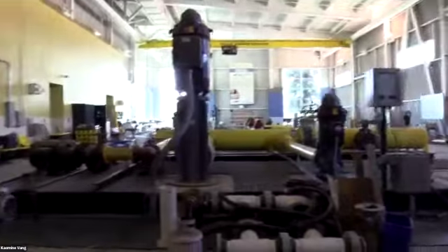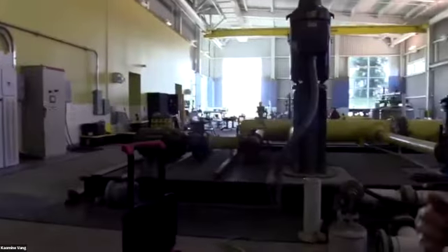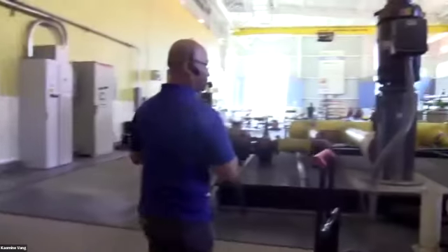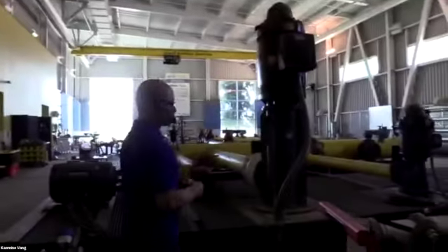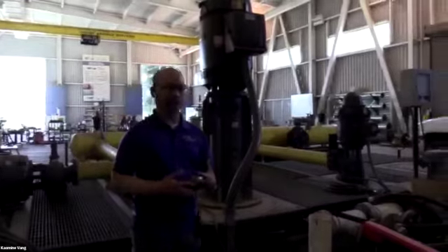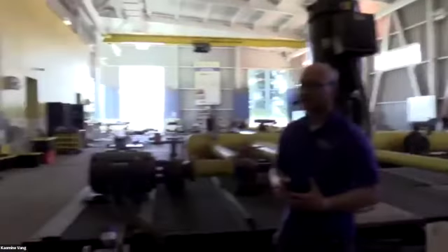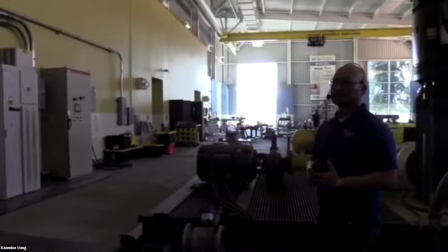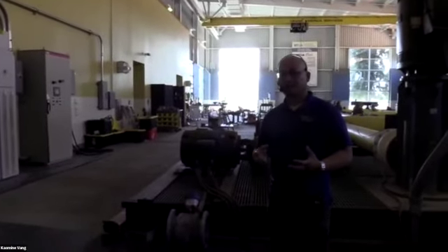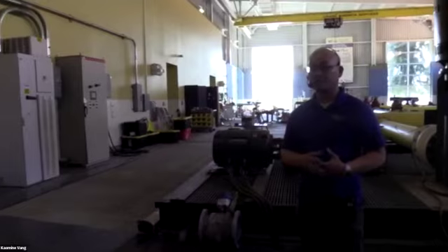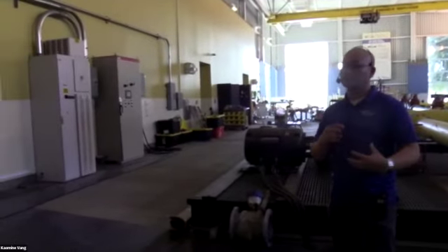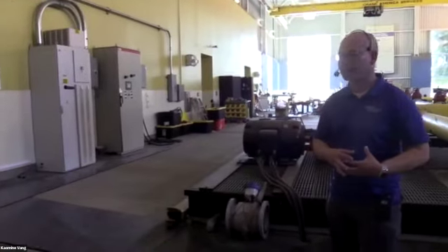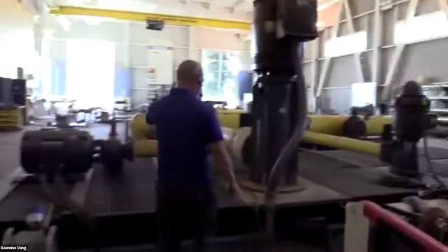Since this session is primarily focused on VFDs, I'm going to talk a little about what we have here. We have multiple pumps in this laboratory so that we can hit the different hydraulic features that we're looking for. The lab runs from 0 to 6,000 gallons per minute and also has a range of 0 to 200 pounds per square inch, so PSI. To initiate that range, we have to have VFDs to do the job. So we have a 300 horsepower motor pump here.